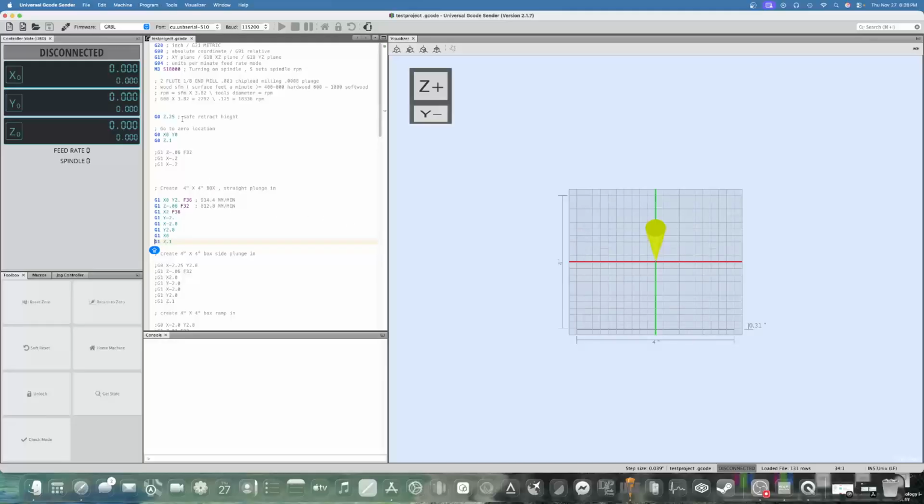Okay. Now on these machines, G0 is rapid, meaning you tell G0 it's going to travel at the firmware set rapid speed wherever it goes. It's normally not ideal, like you see here where I got my Z. I stopped the Z 100 thousandths above the workpiece. You can run that down to 0, but oftentimes you'll get like a little nudge into it or whatever. And that's not the best on the tooling.